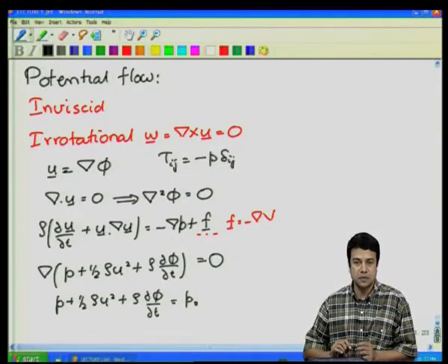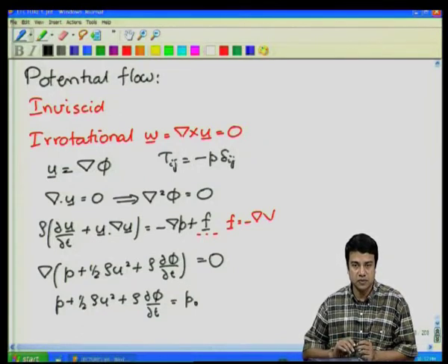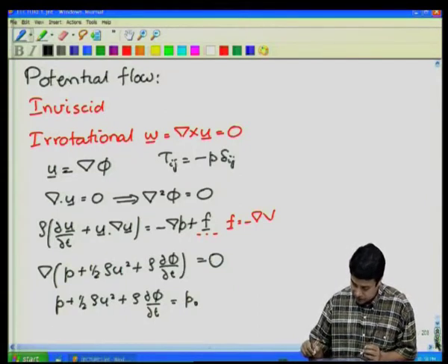For a sphere, we saw that the added mass is equal to half the mass of the fluid displaced by the sphere. For objects of other shape, one can still calculate an added mass either from the kinetic energy or from the force, either from the total kinetic energy of the flow field. So, in that case, the kinetic energy will be equal to half added mass times u square, or from the force required. And in general, that will be some other fraction of the mass displaced by the sphere. So, in the last lecture, we had restricted our discussion to two-dimensional potential flows.